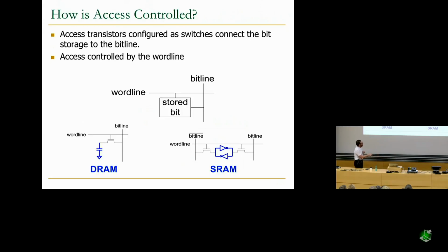And you have 2 access transistors over here. And when you enable the word line, these transistors act as switches. You have the bit line bar over here and bit line over here, and you do differential sensing at the output to figure out whether this was a 0 or 1. So you need some sensing circuitry to sense what the data that you've stored is. We're not going to talk about that sensing circuitry as much in this course, but assume that it exists.